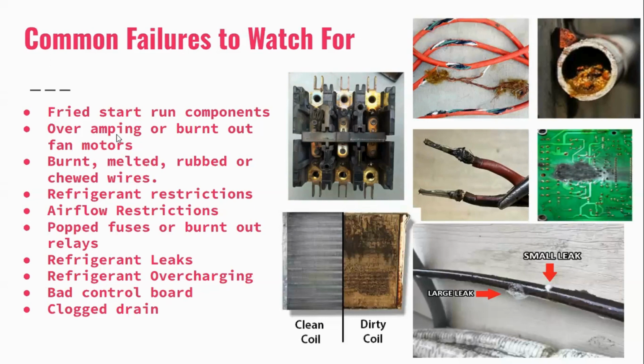So always, it doesn't matter what you're there for, take your little amp clamp and stick it around the wires to the fan. It's not a lot of wires. It takes about 5 seconds. Do it and make sure you're not overamping and burning out fans right after you leave, because that is not a lot of fun. But if you do check a fan and it is overamping, replace it. That could be your problem depending on what the call was for as well.